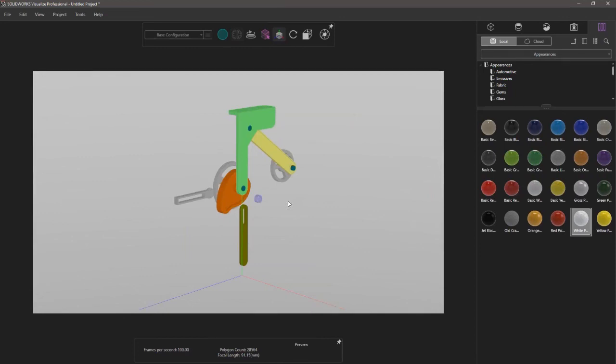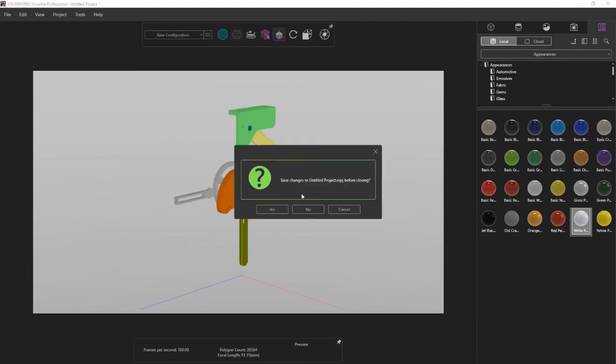So that's really the content I had prepared for today. Hopefully some of these tips were helpful. We started off basically covering the import process from SOLIDWORKS, exporting the model in a simple way where we did the appearance grouping. And we looked at some of the things you can do in SOLIDWORKS, like defining your cameras, decals, appearances, to streamline your workflow in Visualize. We compared those simple and advanced options, to where if you want to move the model in Visualize, you want to be using the advanced export or the automatic grouping, as it's called when you do it from Visualize. Automatic grouping on this end.